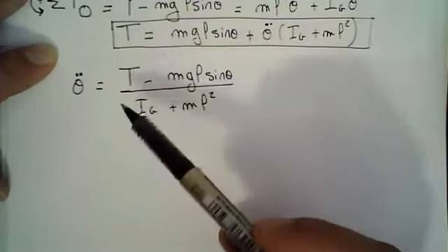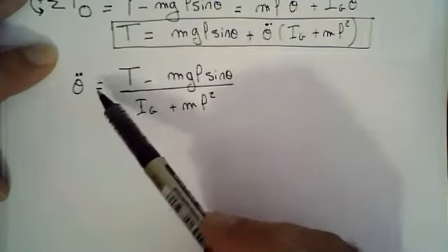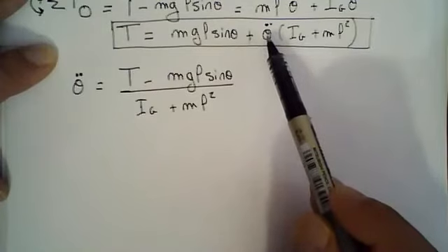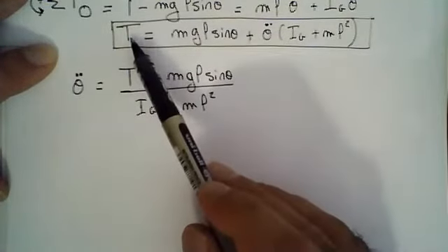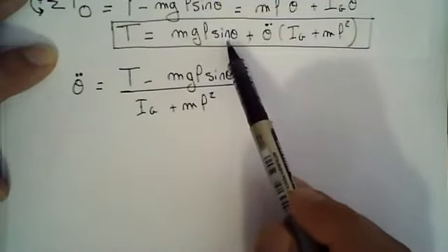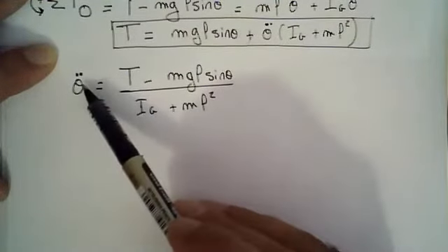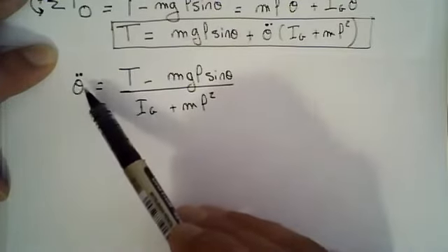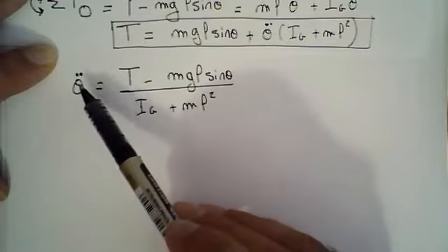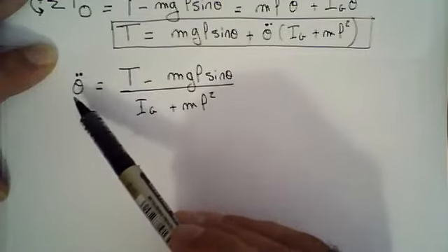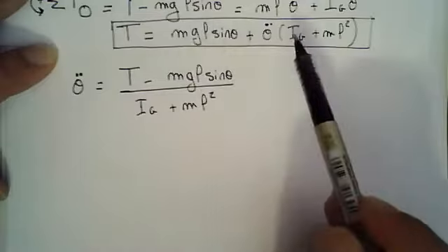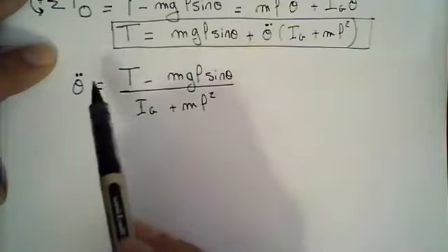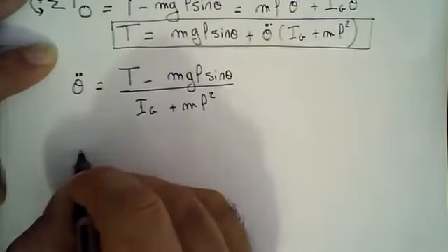One way that I personally like to use is the numerical technique, which is very basic and very easy. Just get the acceleration from the equation, solving for the acceleration in terms of external forces applied on your system and the current position of the system. So now I have the acceleration. Whatever torque is at that geometry, I have a particular angular acceleration. Given that I have theta double dot, how can I find the position? The goal of solving a differential equation of motion is to find the position as a function of time. But now we don't have the position directly, we have the acceleration. So the best way is to integrate the acceleration.